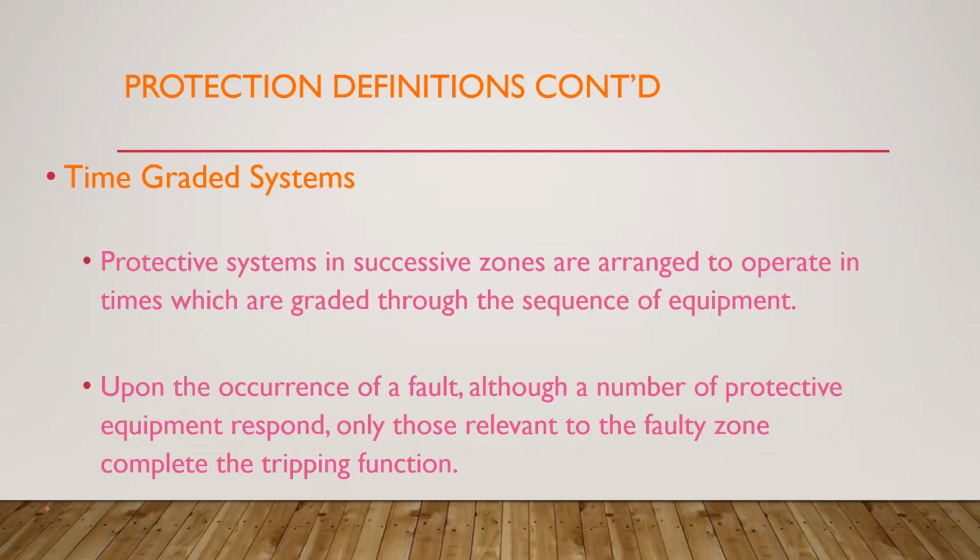Meaning, the person who is going on the live line has a key, and they have what is called lockout and tagout. Some of you who are in the industry may be familiar with those terms. For whatever reason, let me not say it that way, because I want the principle to come home so that you don't go there and carry that attitude. A man just feels lazy and decides, all right, you go and do it. Long and short, the short and ground was not removed before they re-energized the line.